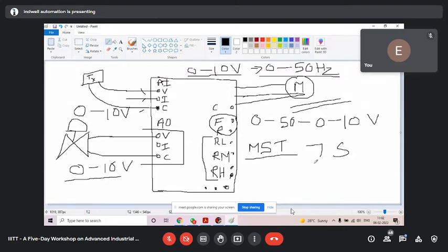It will start and slowly increase, and in exactly 15 seconds, it will be at high speed. If you give it 1 minute, then it will take 1 minute to reach maximum speed. I have given 1 second, so in 1 second only, it will reach maximum speed. I have tried 0.5 also. In 0.5, it goes to overload. So 1 second, I have seen it is okay.